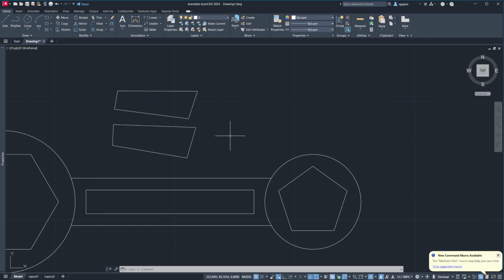For example, if the loop is unclosed, you can't press pull, or you can't extrude it. If the loop is closed, you can extrude it. If it's unclosed, what you create is a surface instead of a whole solid. So it's important that we know when an object is closed and when it's open.